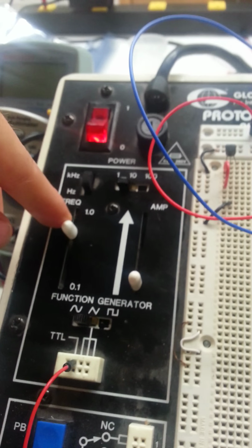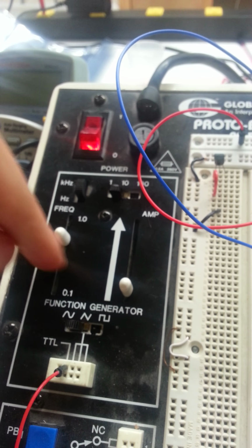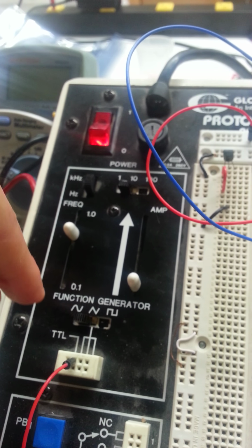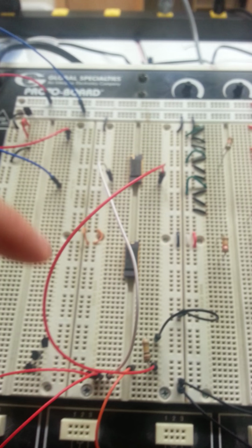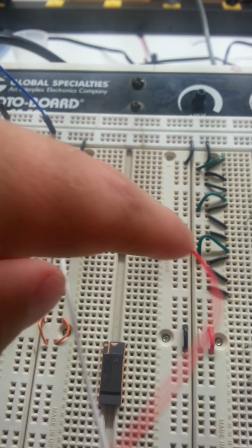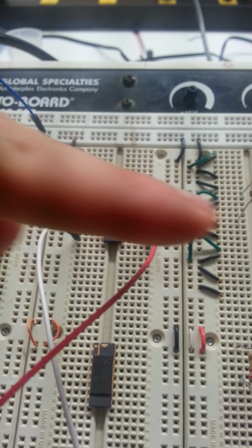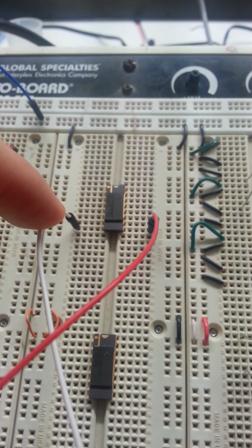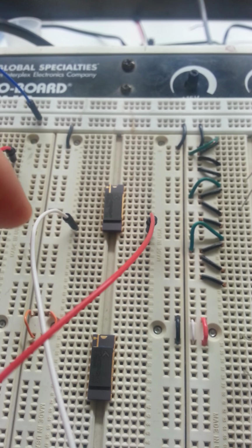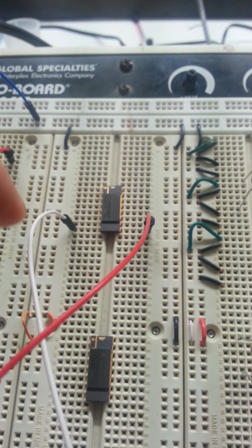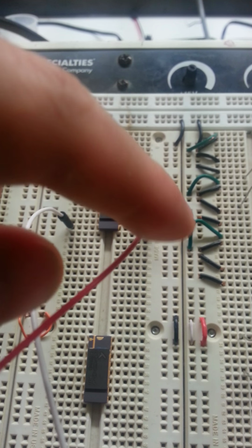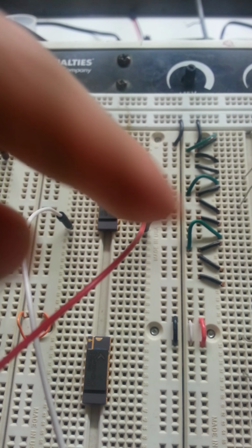We have a variable sine wave generator here. We have it set to about 700 hertz. Amplitude is at 0 currently, and we're putting the signal across the memristor. The memristor here is available on adjacent pins, with the polarity pointing from left to right. So essentially a voltage applied across from left to right, where the right is the lower potential end, will cause the memristor to go into its high conductance or low resistance state.